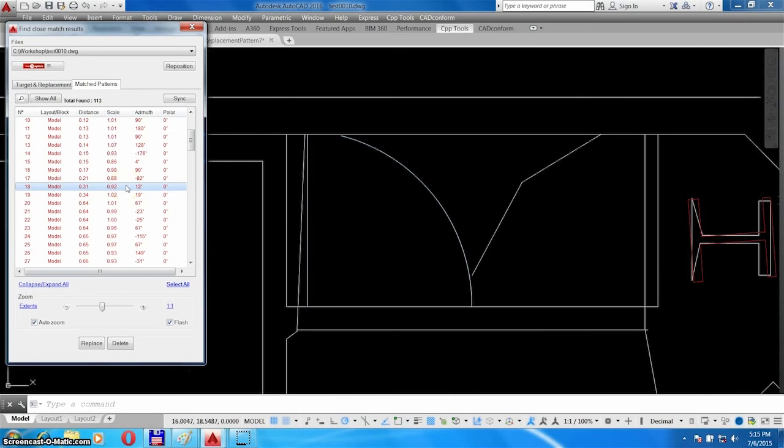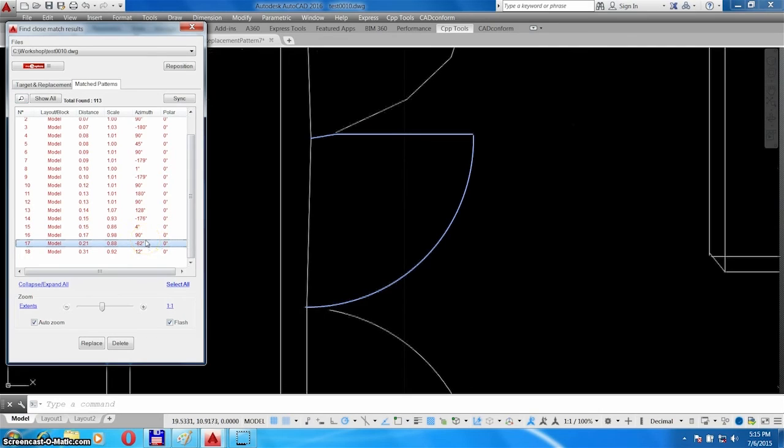This object is the last object in the list we are interested in, so let's set the threshold distance to something like 0.32, delete the scale interval criteria, and as a result there are 18 doors. Let's again select them all, quickly isolate them all, and verify that all of them are objects we are looking for.